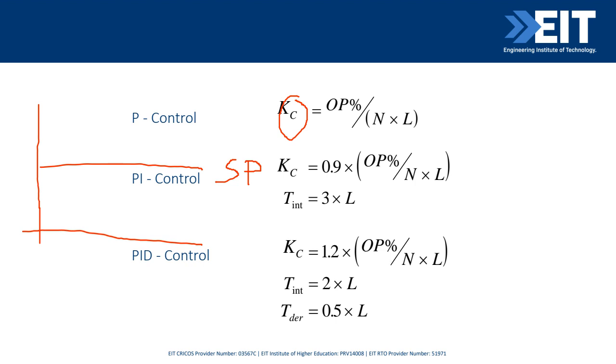And this is the process variable, PV. Sorry, it's like a drunken scroll. Process variable, and what we do is we use integral control, and it actually integrates out that error there. So there's a bit of an error between process variable and set point. As you know, integral grabs the bit of error, and we then use that bit of extra effort in our controller to drive the process variable down to match up with set point.